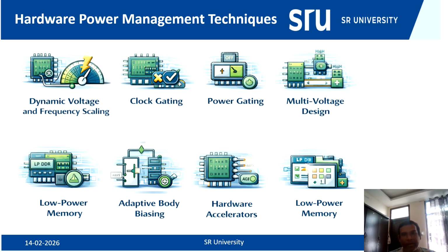If we reduce 5 to 4, then 4 squared means 16. So previously it was 25, but if we change only a small amount of voltage, 1 volt, from 5 volts to 4 volts, you can see the effective value is reduced by approximately 9, because when VDD is 4, VDD squared is 16.